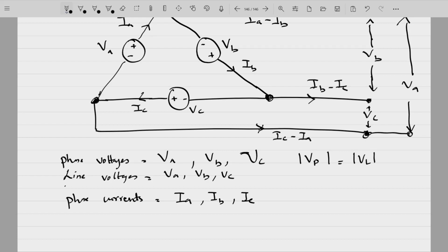अब IA, IB, IC का value तो हमें exactly we do not actually know the values of IA, IB, IC unless there is a load connected. Only then we can calculate the values of IA, IB, and IC. But from here you can actually say that at least you have established that in case of a delta connection, the phase current and the line current will not be same. ठीक है, तो जब हम लगाएंगे कुछ लोड, तो हम देख लेंगे कि वो line current will be actually root 3 times the phase current.